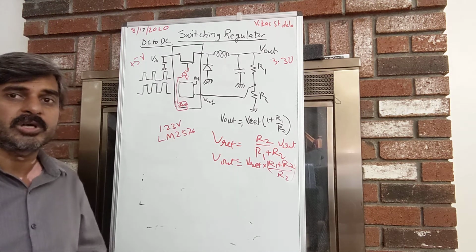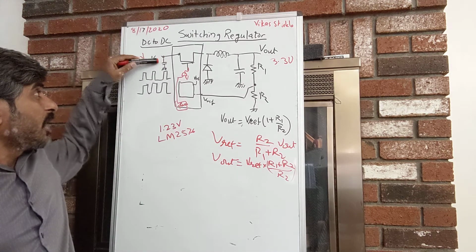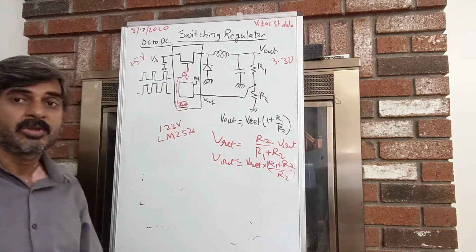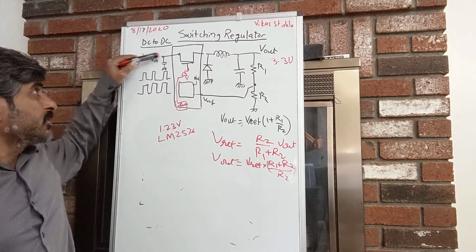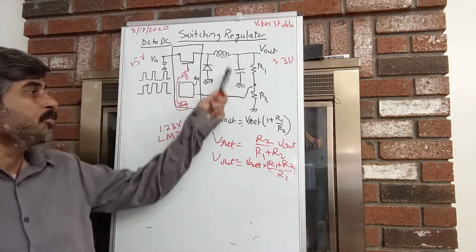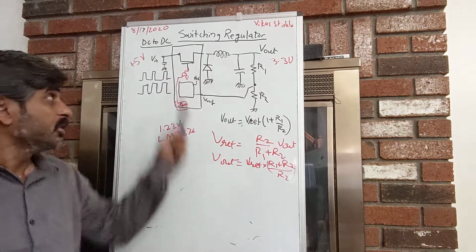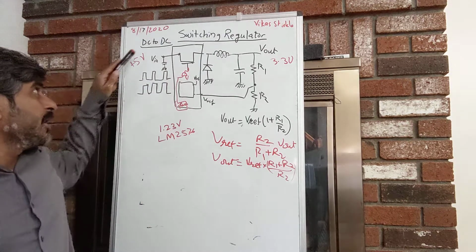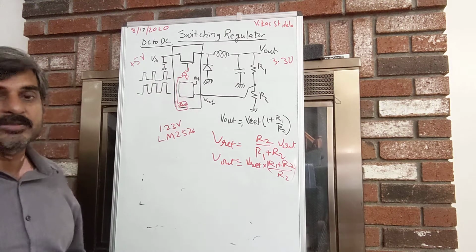One of the most critical things is this small capacitor at the input of this chip, and this is often ignored because you may think we are only concerned about the output capacitor to reduce, for example, ripple at the output. You may think we can have one big bulk capacitor, that's it. So what's the use of this small capacitor?